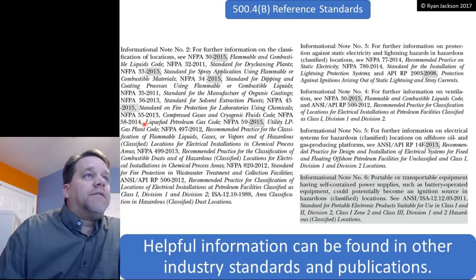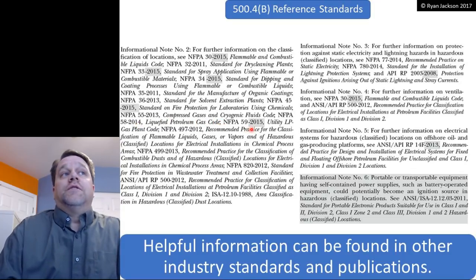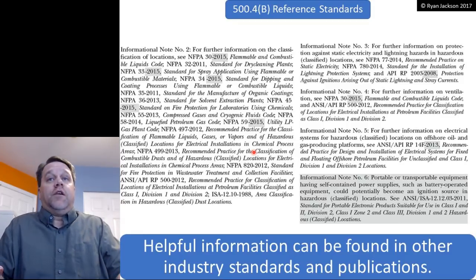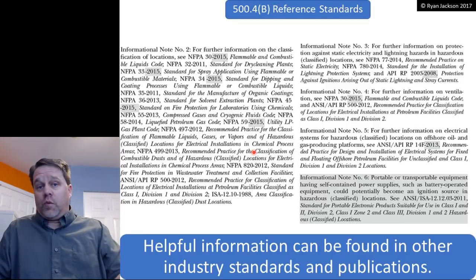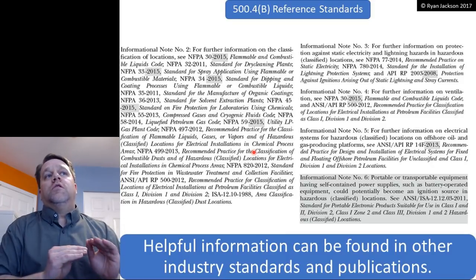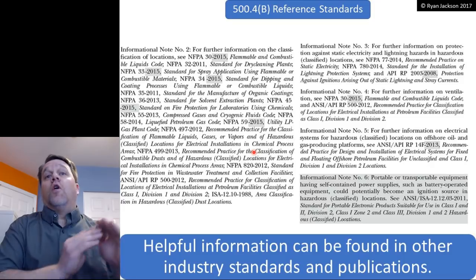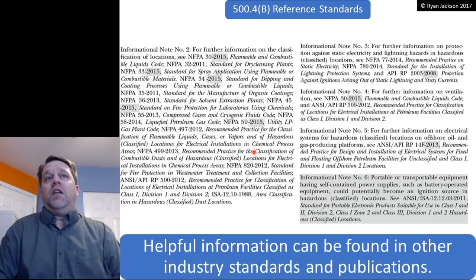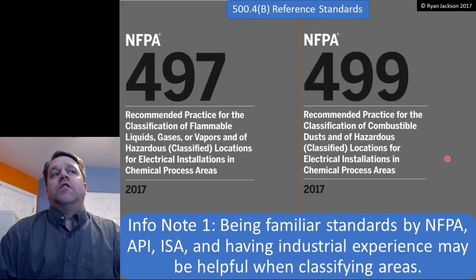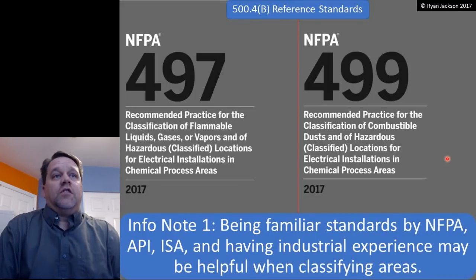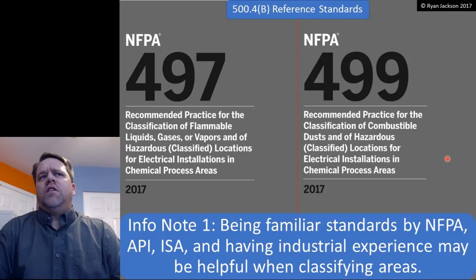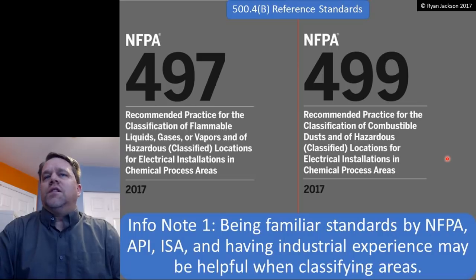NFPA 55, compressed gases and cryogenic fluids. If that's your world, then you probably ought to have that document. If that's not your world, then there's no reason to go out and purchase that document. But we do want you to be aware that there are standards for just about anything that you can conceive of. Another note says being familiar with standards by NFPA, API, ISA, and others, as well as having industrial experience may be helpful when classifying areas.